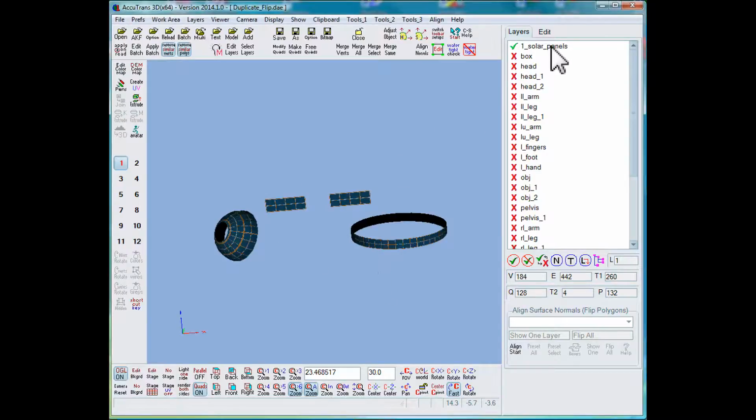Now I'm going to click with the left mouse button and hold it down for a bit, then release it, and this is kind of tricky to get in. I'll try it again. Okay, there we go. Now we can edit the name in place here, take off that, and I'm going to put back on here as I'm making this the back layer. Press the return key and this layer is now called solar panels back.